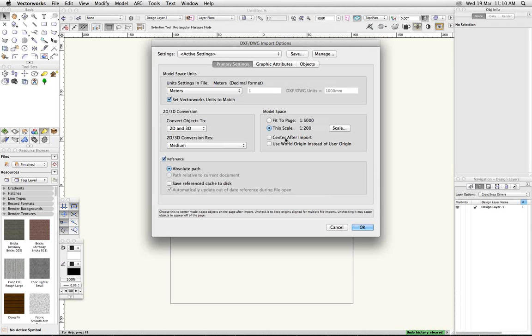And in Vectorworks, and in fact in any CAD and modeling program, problems can creep in at extreme distances from origin. So this is a method that you'll need to use if you get geo-referenced files, and this will be particularly important if you need to work back and forth with other consultants and they expect that what you send back is going to come back to them at the same coordinates. So we do this, click OK.